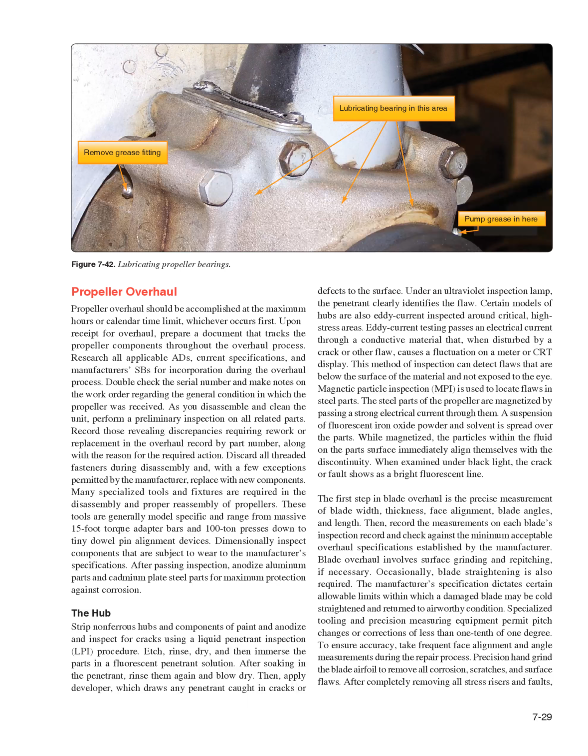Propeller overhaul should be accomplished at the maximum hours or calendar time limit, whichever occurs first. Upon receipt for overhaul, prepare a document that tracks the propeller components throughout the overhaul process. Research all applicable ADs, current specifications, and manufacturer's SBs for incorporation during the overhaul process.